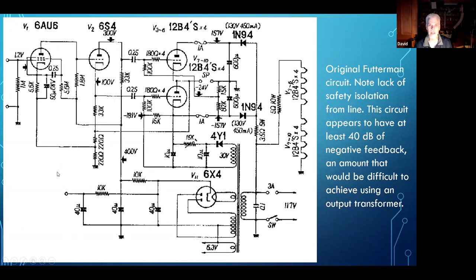If you were designing a modern day op amp, this is the ideal way that you would go about it. You want that dominant pole so that you can get very, very high stability. And that's the key to being able to apply a lot of negative feedback: you have to have that stability, and you have to have that single dominant pole and no other screwy things in the circuit to affect phase shift anywhere near where that dominant pole is working. And if you study the circuit with that in mind, you can see that, hey, this is actually pretty good.